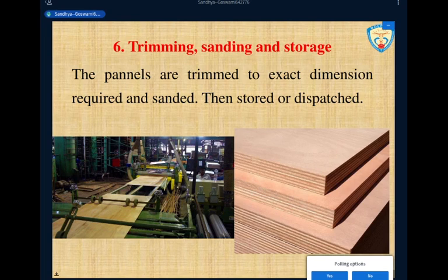So if you put the PF on any surface, it requires heat to get crystallized quickly. Without heat, it will not give good results. It will not get crystallized. It will not join the two surfaces. That is why we need hot pressing. It will not work in cold pressing. Okay? Did you get it now?